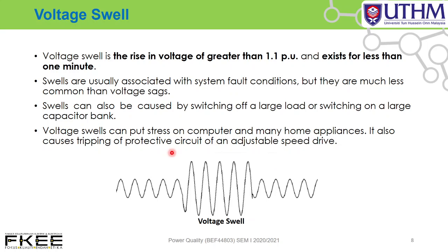Voltage swell can put stress on equipment. What is the effect of voltage swell? It can put stress on computers, electronic devices, and many home appliances. It also causes tripping of the protection circuit of an adjustable speed drive, because the voltage suddenly increases, maybe beyond the setting and so on.